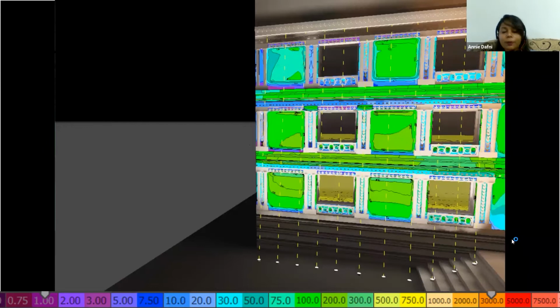So when you're talking about the lux level, since you're placing the fixtures very close by, what happens is it creates a very nice gradient effect on the surface. So there is no uniform illumination, but the lux level is much higher at the bottom of the wall, which is closer to the fixture. And as we go away from the fixture, the lux level reduces gradually. But still, you will get an increased lux level of 100 at the top, depending on the number of fixtures and the wattage that you're using. And at the lower portion, you'll get a much brighter output of close to 200 in this case here.